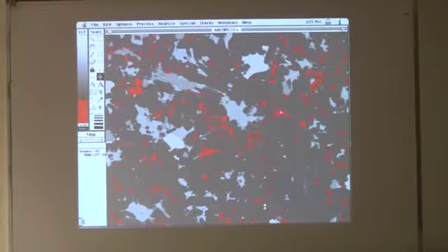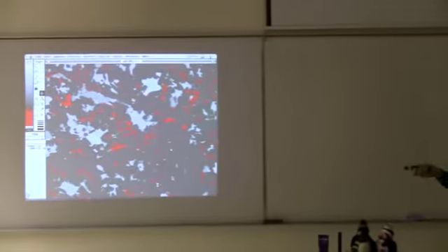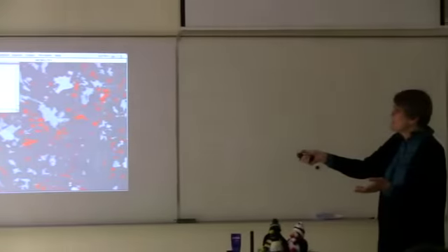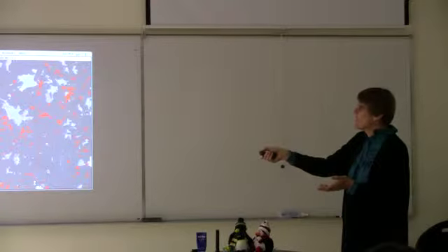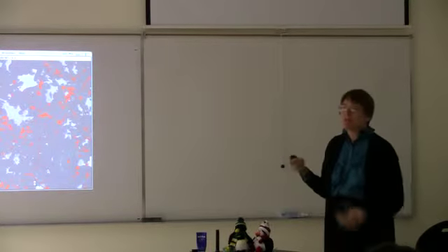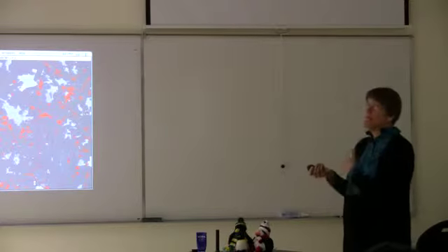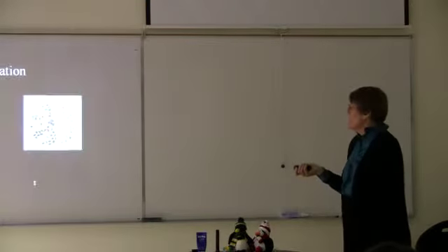But it's just filling the red into the pore space, counting the number of pixels that are red, and then the computer records those two pieces of data, so you just do a simple calculation: the number of pixels that are red divided by the total number of pixels gives you the percent porosity, the percent empty space in that image. And so it's a real slick, easy way to do it if you have access to lots of backscatter electron images.